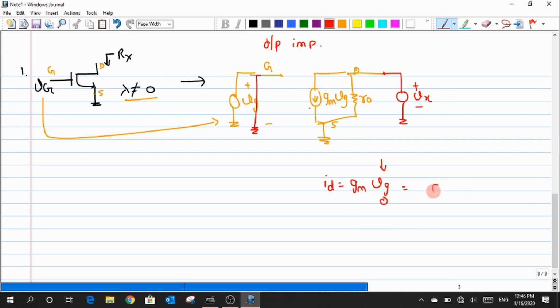The current is also equal to 0. How will you represent the current? It's an open circuit. So what I do is I just open out this particular point. I've just created an open circuit between the node of source and the drain. Now what is left over is just the R0, and now how will I measure the current Ix?